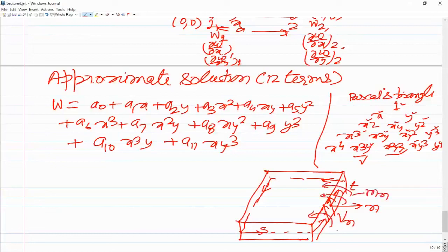Now the work done by Vn is going to be Vn into W, because Vn is in the W direction, the displacement force in the direction of W. So work done is Vn into W, and then the potential is negative of that. That is how I have written the integration over the boundary with a minus sign, W transpose into Vn.